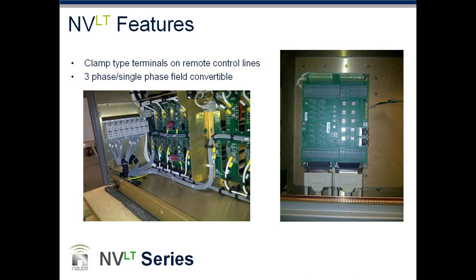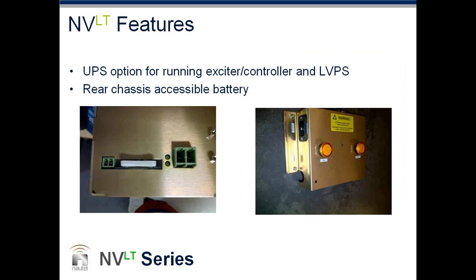Okay. That's just another shot of the lower AC portion of the transmitter. We pre-install ferrite on the AC line to help with maintaining balance on the lines and keeping RF out of the AC. And improving lightning protection as well, correct. Yeah, and then this is the remote control card, with the buttons we spoke of that can be programmed for auxiliary control.